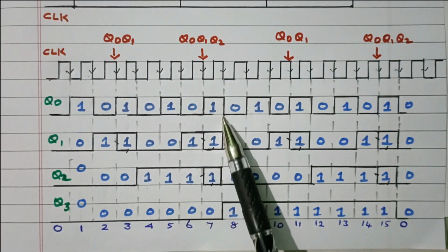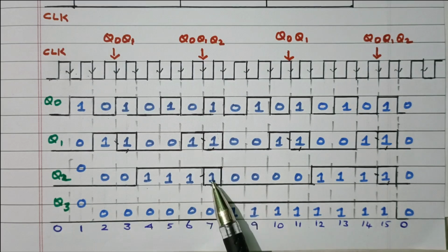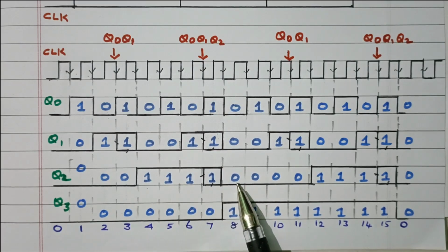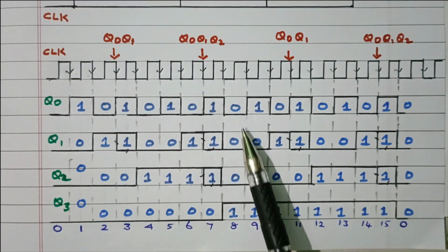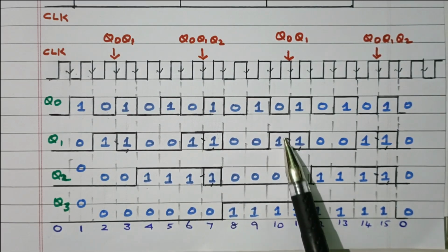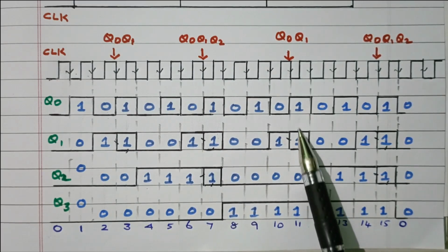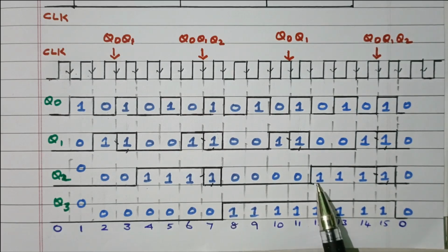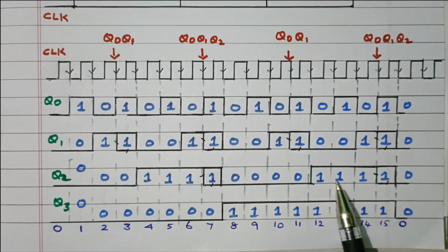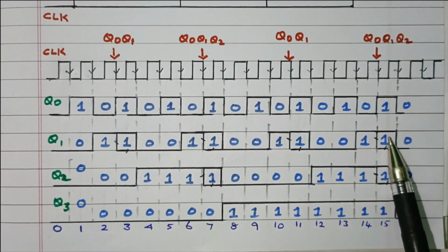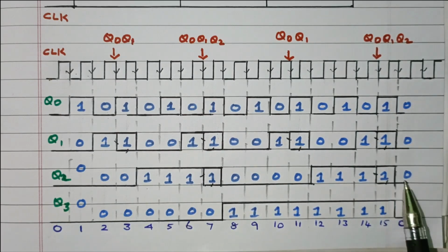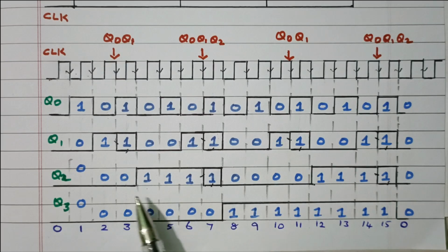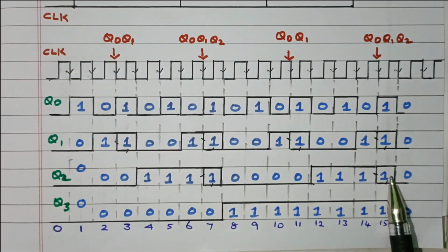Here again 1, 1. So again it changed from 1 to 0. Then again 0 is continued, because this is 0, 0, 1, 0, 0, 1, no change. Again it is 1, 1. When 1, 1 occurs, toggle from 0 to 1. Then it maintains as it is until the next 1, 1. Changed from 1 to 0. Right? So this is the output of the third flip-flop.